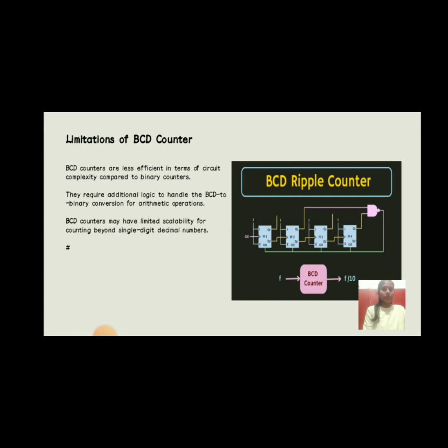Limitations of BCD counter. BCD counters are less efficient in terms of circuit complexity compared to binary counters. They require additional logic to handle the BCD to binary conversion for arithmetic operations. BCD counters may have limited scalability for counting beyond single digit decimal numbers.